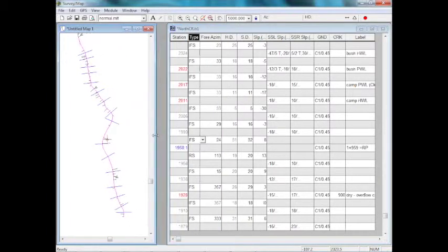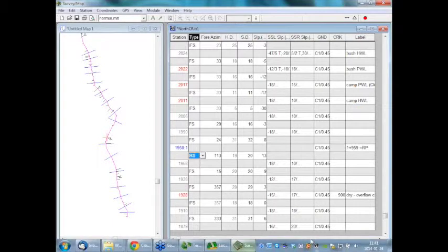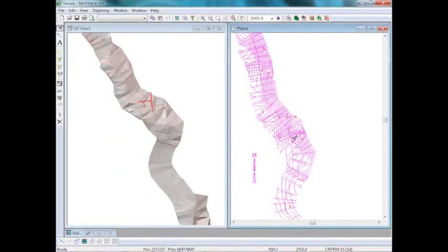I just clicked on it so it becomes the current point, and there it is. So azimuth, slope, distance, it's created a 3D point. And you can create as many of those as you want. So in an area where you want to define the three-dimensional surface better, you can create a bunch of radial shots. When you bring that into terrain, you get a better surface because it uses those 3D points. Okay, so I can create a 3D surface from my survey with side shots.